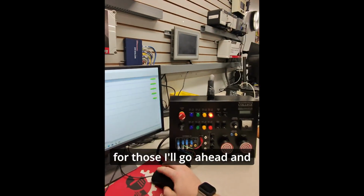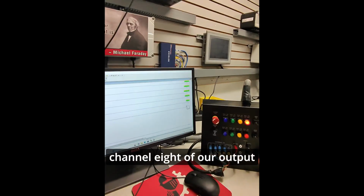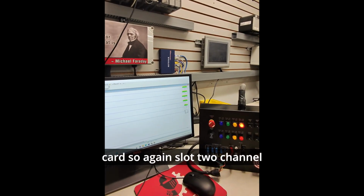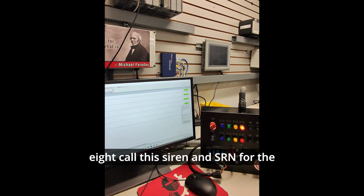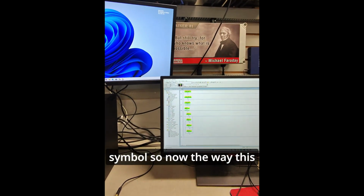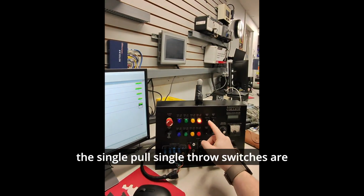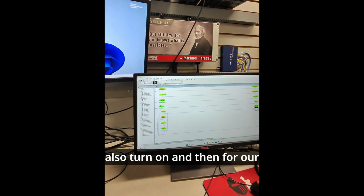For those, I'll go ahead and tie them to the siren. The siren is channel 8 of our output card, so again, slot 2, channel 8. We'll call this siren and SRN for the symbol. So now the way this logic will work is if any of the single pole, single throw switches are turned on, our siren will also turn on.